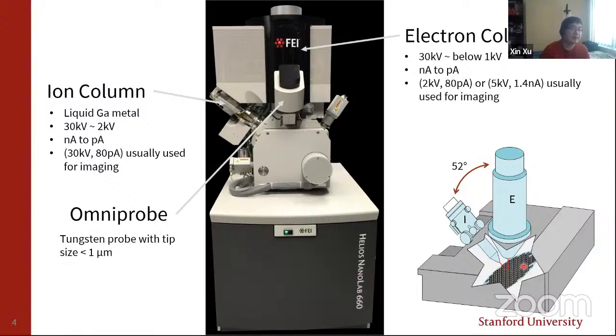In this chamber, you can choose the sample stage to let your sample face the electron beam or the ion beam. In this way, you can change the mode between the electron and the ion beam mode, during imaging, etching, or deposition, which I will also talk about later.